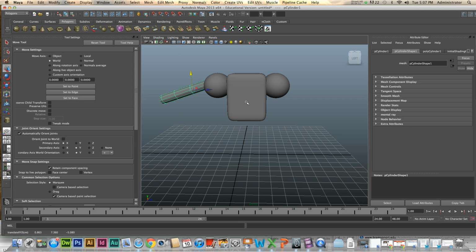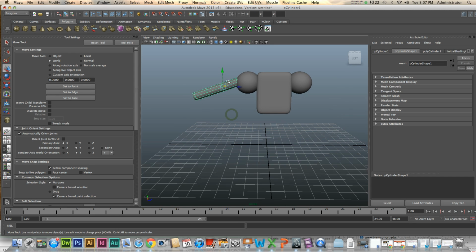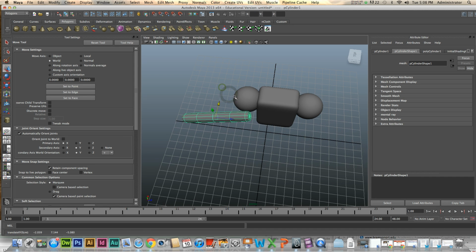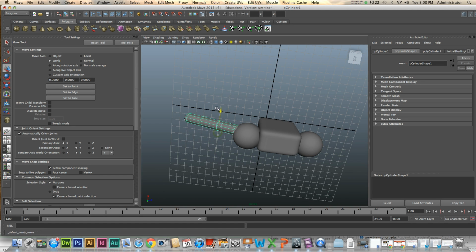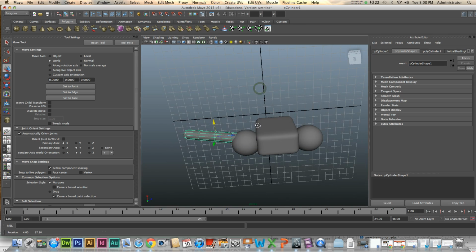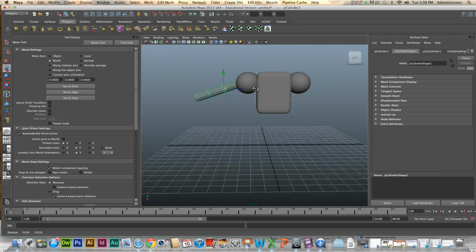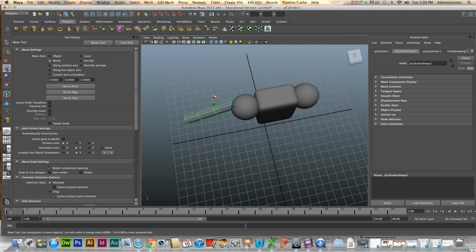Always remember to hold down Command and look at it from 3D space. Otherwise, you might think you're putting it in the right direction, when in fact, I'll give you an example. You might think you're putting in the right direction, but when you look over here, the geometry is not placed correctly. So always make sure you look from the top, you look from the bottom, the side, okay, and make sure that placement works for you.